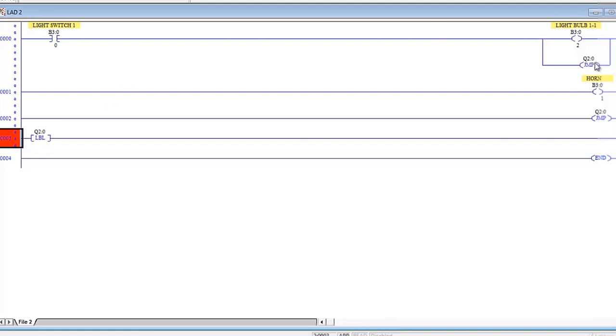which means you'll have your jumps and the logic that's possibly going to be skipped depending on the conditions above, but usually right before your label rung, you'll have a jump rung just in case nothing above happens to jump to it. Then as a last ditch, even though there are no conditions, you'll go ahead and jump to that rung unless it's something that you only want to execute under certain conditions.